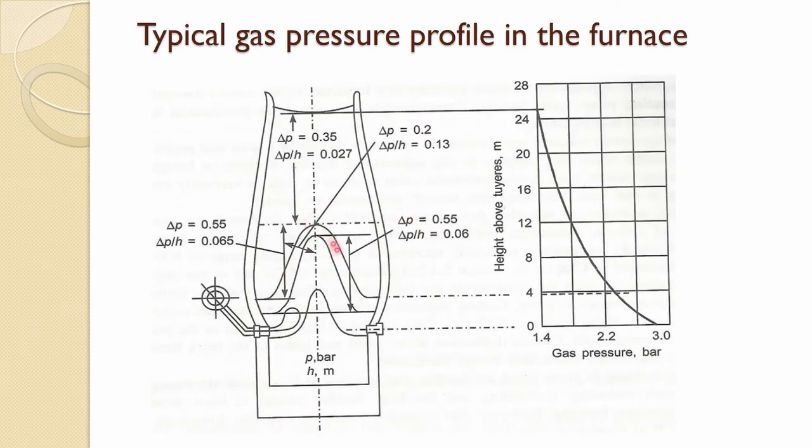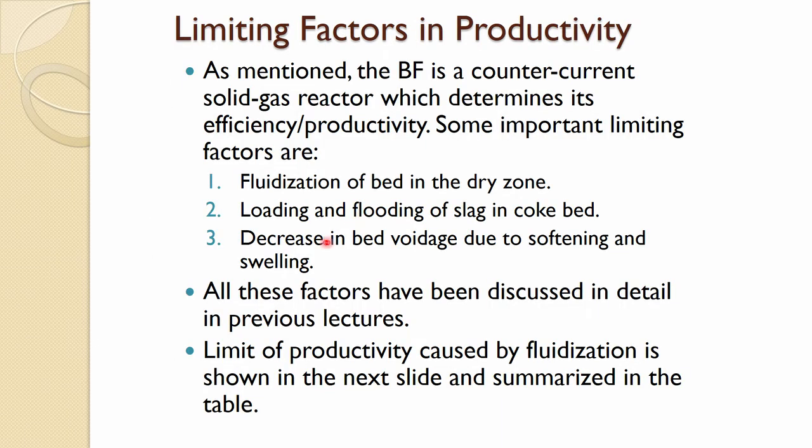So, with respect to that, because the slag and liquid is flowing down, voidage is reducing, and so that will carry away more liquid and it can deteriorate if this is not maintained. Velocity is high, more fluidization, because you have a smaller particle size here also. So, fluidization may occur localized one.